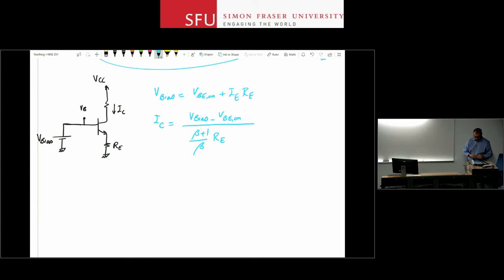Now, let's look at this circuit for a while. The inclusion of that resistor in the emitter circuit is going to solve a lot of those problems we had with regards to instability of the bias point. For example, let's assume that you would like to have 0.2 to about 1 volt of voltage drop across this RE. This is your typical bias condition, and we know that there are drawbacks for putting a lot of voltage there. So if you use half a volt here, your V bias is on the order of around 1.2, 1.3 volts.